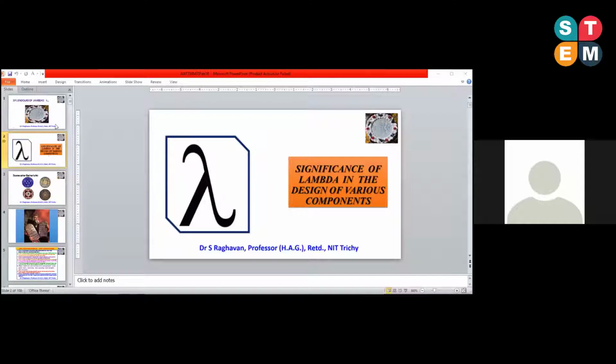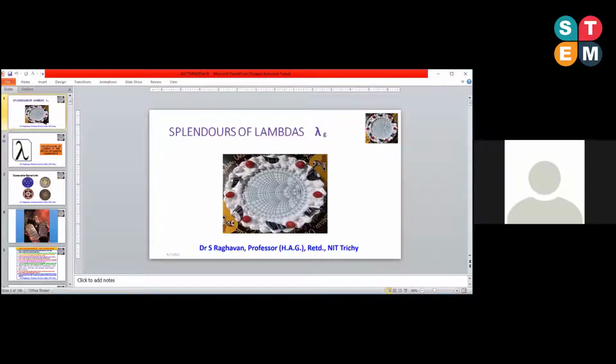one is the manufacturer's concern. Unless otherwise specified, in the whole world it is 1/16th of an inch, or you can call it 1.6 mm. So one need not bother about the height of the substrate. What one has to design is the length and the width of the components. Components, I mean, what one can print or use in the satellite.